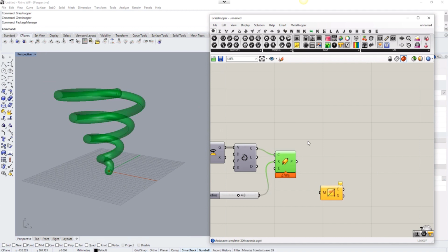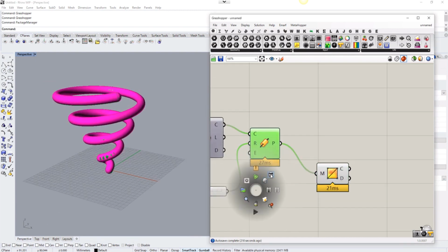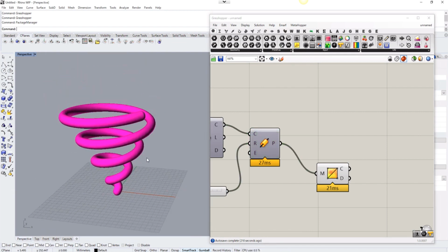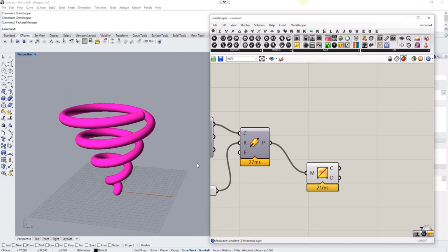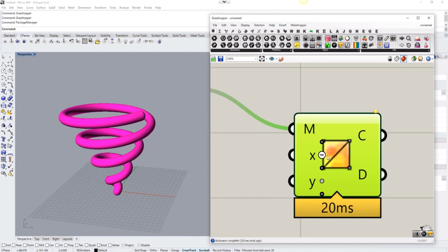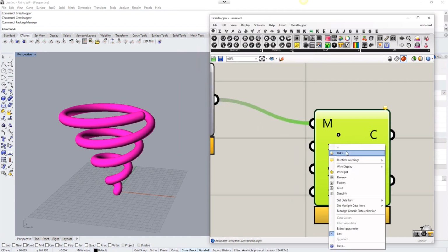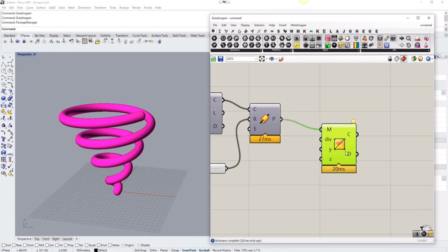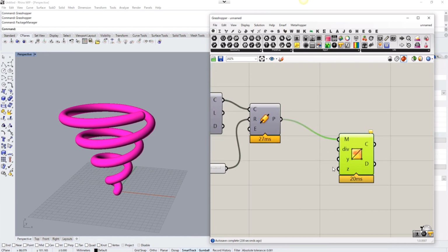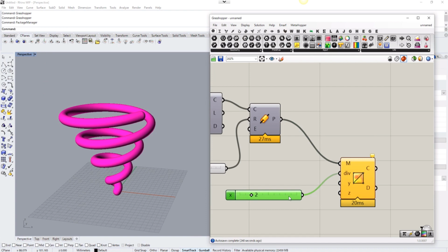Now let's connect this pipe into the mesh shader. As a default, you have this magenta diffusion shader, and we're going to build up some new functions based on this. Okay, first of all, I am going to add some parameters that we're going to use. Three parameters. The first one, I'm going to call this div, as a division number of how many shades you would like to have for a Toon shader. So it's going to be an integer, so I'm going to make an integer slider here.